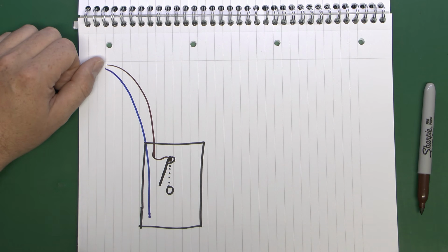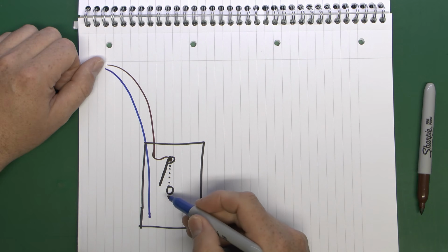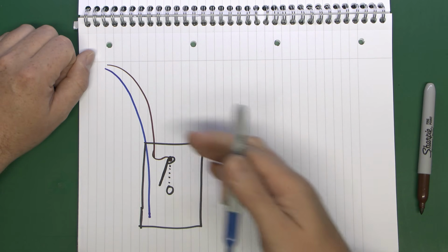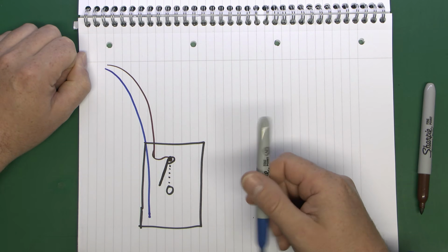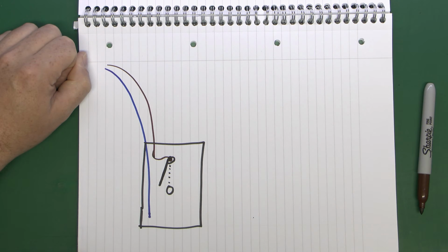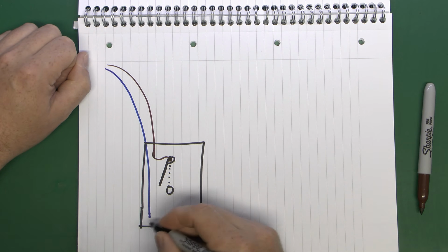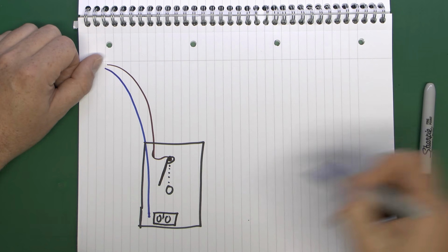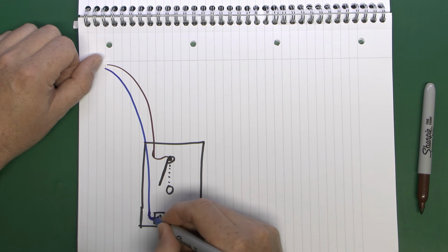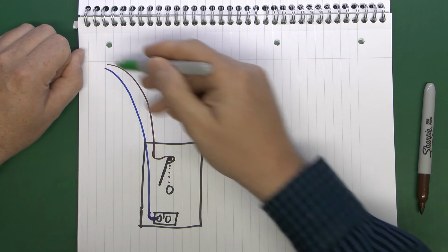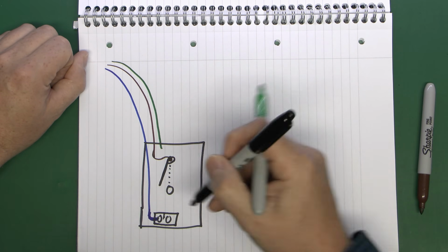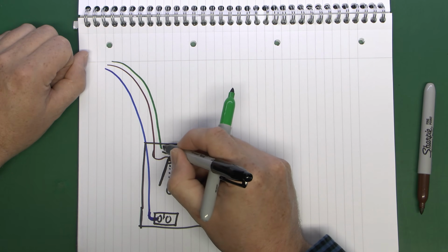but the neutral there, of course, does not connect to the switch, because if you put the neutral here, when you turn the switch on, you've shorted out the mains, there's going to be a big bang and the switch is going to be destroyed and fuses are going to be blowing and everything else, so obviously the neutral does not connect there. So what you actually need here inside the switch box is a separate terminal, usually with screws or something in, and that's where the neutral goes, so that goes in there. And just before, we of course would have the earth wire coming down again, which will be joined in yet another terminal at the top here.